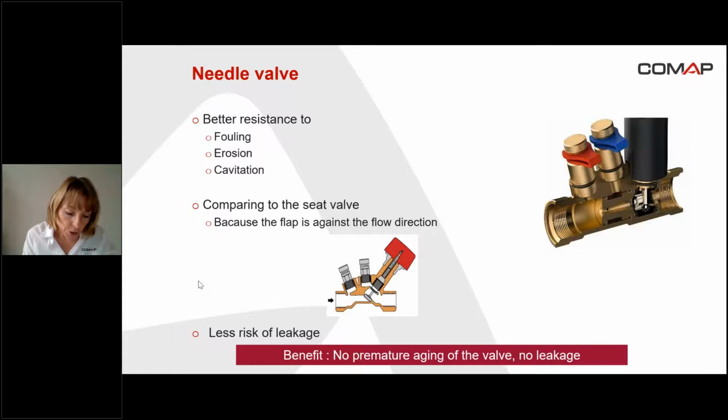To explain the cavitation in two words, it's when there is a pressure drop just before the valve, and because of this pressure drop, the fluid vaporizes. Just after the valve, the fluid is going to condense, and this phenomenon generates a shock wave which is 7 times higher than the steel can withstand. So it causes a lot of damage to the pumps and to the valves. So it's really important to pay attention to the cavitation.